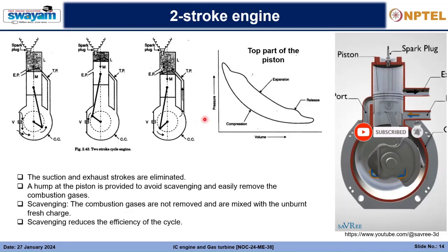So here the interesting thing is that you see that the exhaust port is above, the transfer port is a little bit below, and the inlet port is out here. Somewhere the inlet valve can be here, somewhere it can be there, but that doesn't matter, because eventually the whole piston is driving the air out here, and we are not considering that in this part of the system. We just need the air to go in and come to this part, which is happening only through the transfer port. So the transfer port is a little bit down.